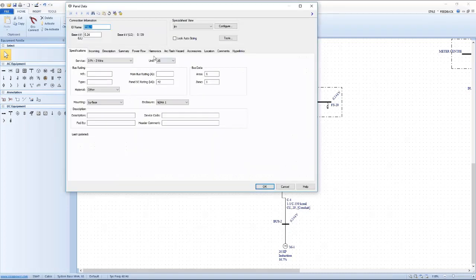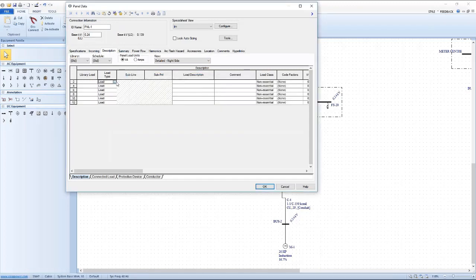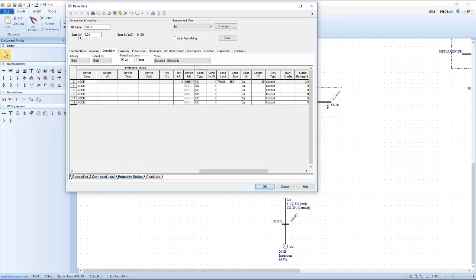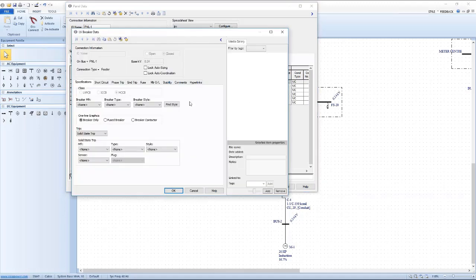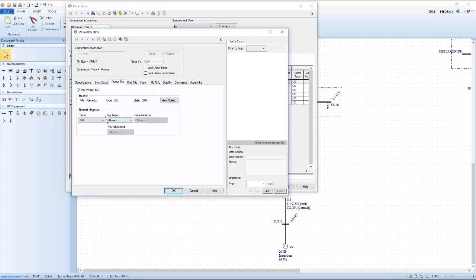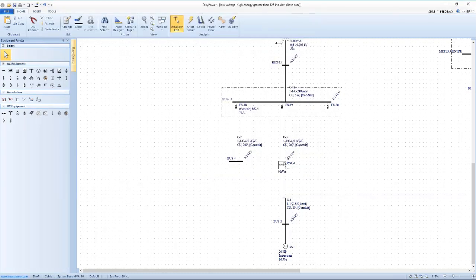and I go in and look at my panel description. Let's say we have 6 circuits. One of those circuits needs to be a sub panel, and at that point I pick out which cable it's going to, and it'll give me a sub panel down there. As I go over and look at what's loaded, it knows which cable I'm connected to, but it doesn't know what that load is. So when I go to size up that breaker, I need to designate inside the panel structure what the characteristics of this particular breaker need to be. And consequently, by setting this up for 30 amps, now we can create a downstream arc flash label even though I'm using a panel schedule.